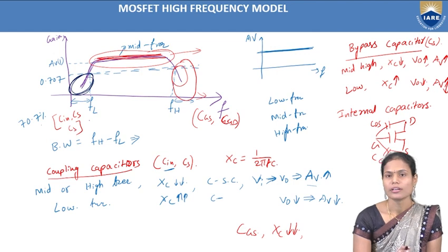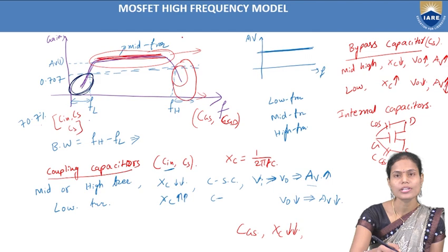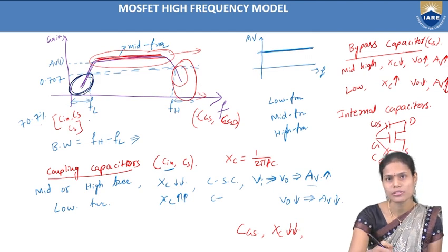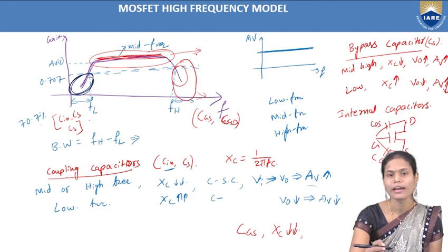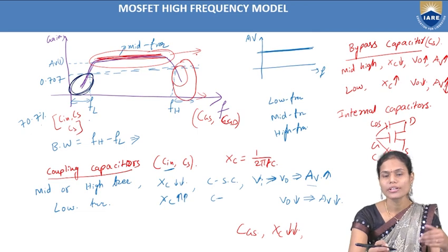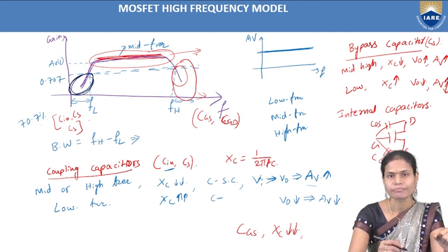From a practical amplifier also we need to get constant gain, but because of all the capacitors' effect we are not getting constant gain for all the frequency ranges. And this frequency response is not similar for all types of amplifiers. In the common source amplifier it may be different, in the common gate it is different, and in the common drain amplifier it will be different, and also at different frequency ranges. And because of different coupling schemes also, this frequency response will change here.